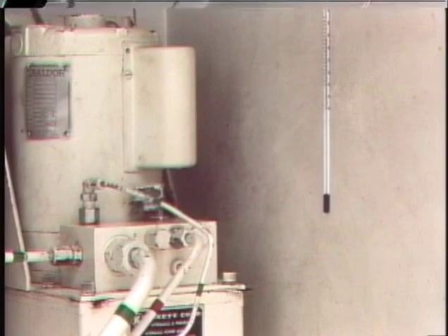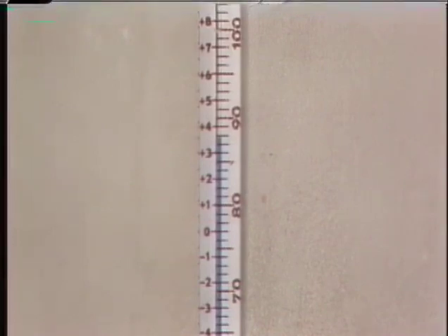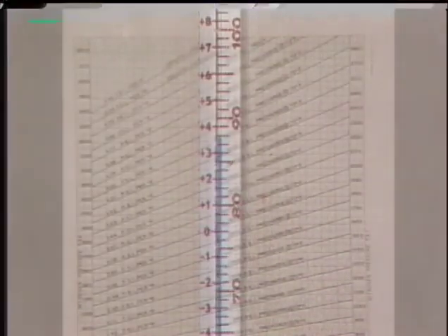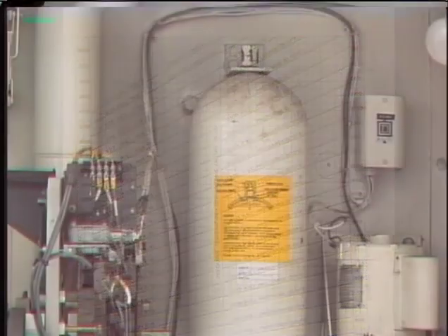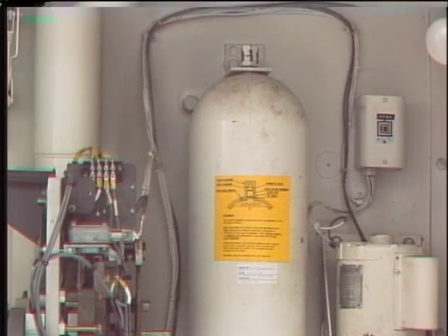Acceptable pre-charge pressure is usually a pressure value at a given temperature. If ambient temperature is different from the given temperature, the pressure must be adjusted to compensate for the temperature difference. The manufacturer usually provides a pressure-temperature compensation chart. Using the chart, you can determine the adjusted pre-charge pressure. If the adjusted pre-charge pressure is less than that recommended by the manufacturer or allowed by company policy, gas may need to be added to the accumulator.